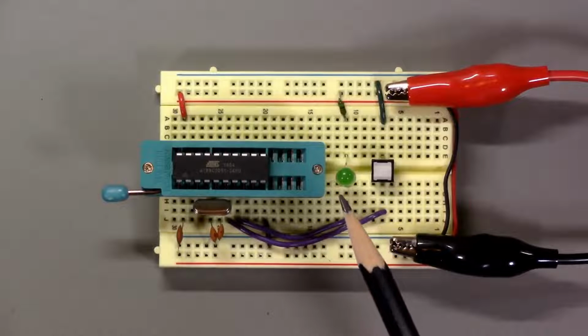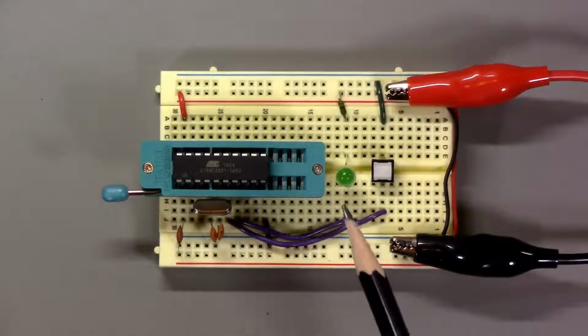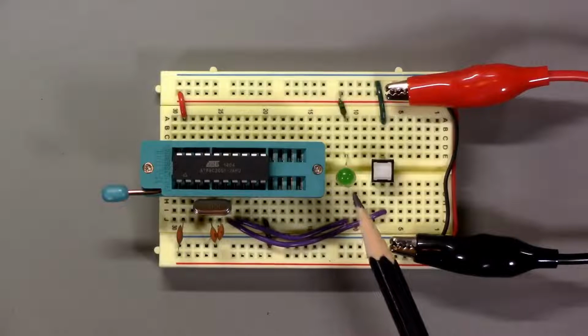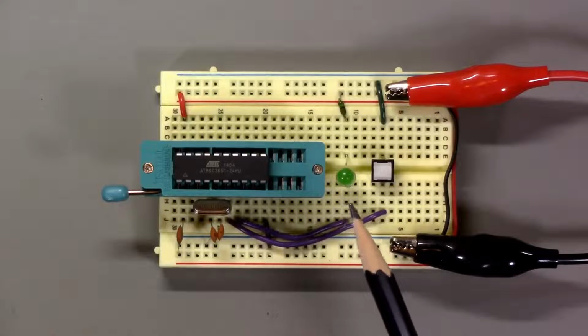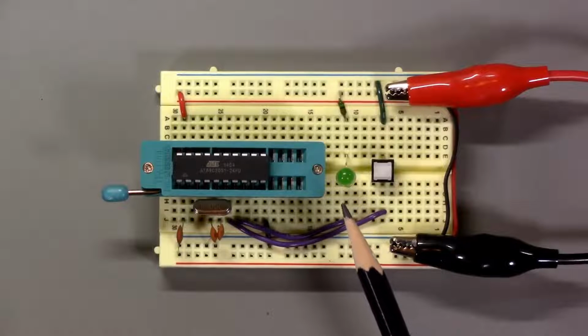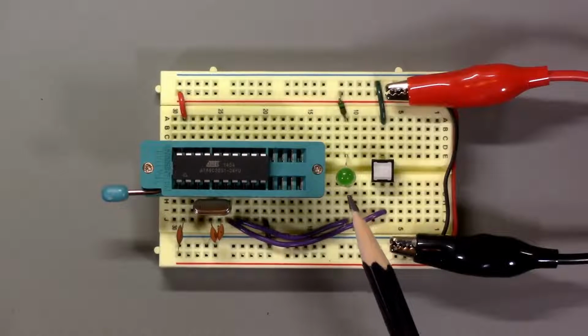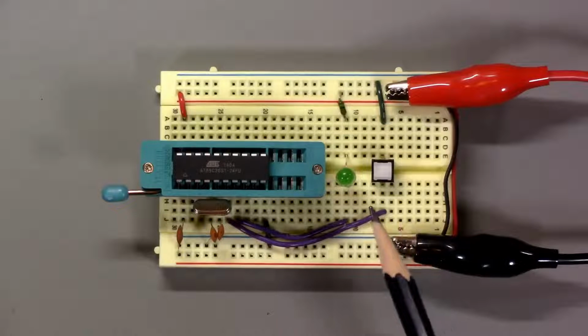So what this seems to imply is that if you want to read a digital input value from a port on an 8051 device, you need to write a 1 to that port first, sort of eagerly. In other words, once an input causes a port value to switch from 1 to 0, it doesn't seem to automatically get restored from 0 to 1. So that's interesting, and it's definitely a little bit different than what you might be used to if you have used AVR devices and Arduinos.